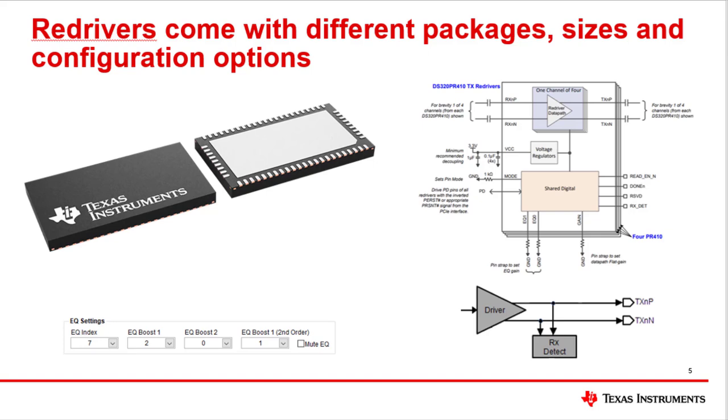The other would be using SM bus mode. This form of communication also enables reading and writing to the device's internal registers to obtain status updates on RxDetect or other functionalities. If you're interested in either of these modes of communication, see the DS320PR410 datasheet and DS320PR410 EVM User's Guide and Programming Guides for more information.